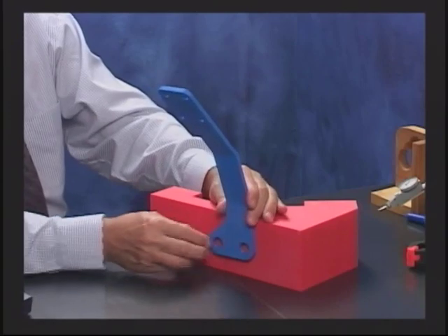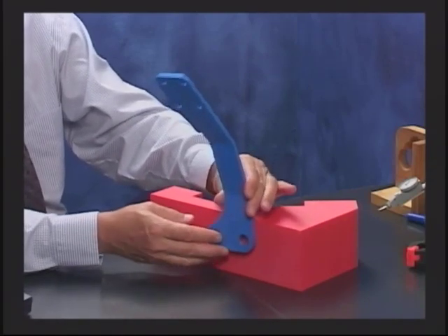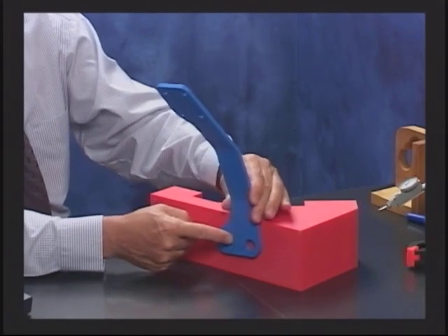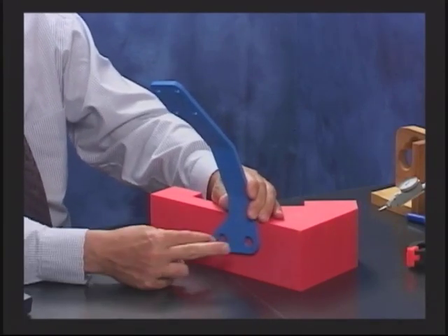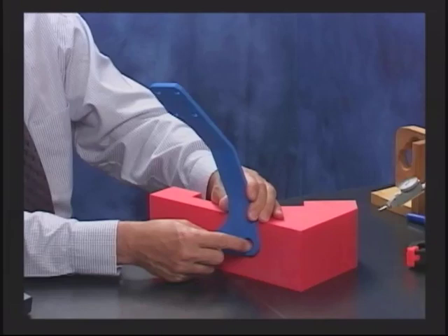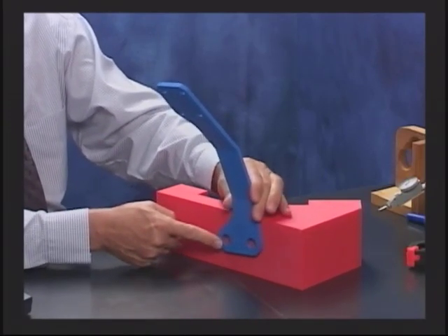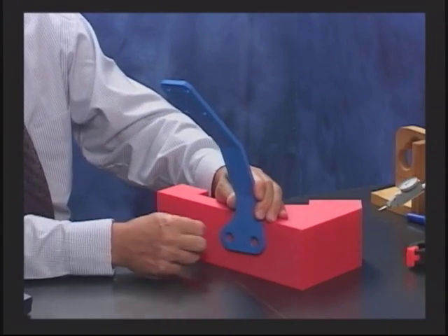Now, if that face was the datum, that sets the attitude, and the primary datum is one of the most important, right? That sets it up. Now, what locates this thing back and forth? What I saw is it was located by these 2 holes. These 2 holes, you notice they do everything. They stop it back and forth. They stop it up and down. They stop rotation. It's the 2 holes.